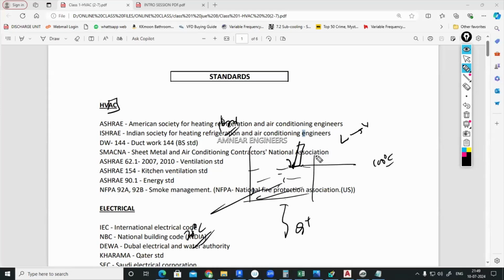Correct. Evaporation of water means from the liquid, the water will be changing the phase into vapor. We will be discussing this in detail in the upcoming classes, psychrometry especially. But one thing, if the water needs to be evaporated, it needs latent heat. Latent heat is the hidden heat the substance is using for phase change. Don't worry, in the upcoming classes, we can study latent heat of evaporation, latent heat of fusion, everything in detail. But just for your knowledge, if the water needs to be evaporated, it needs heat. So all kinds of evaporation, in the background, will produce a cooling effect.